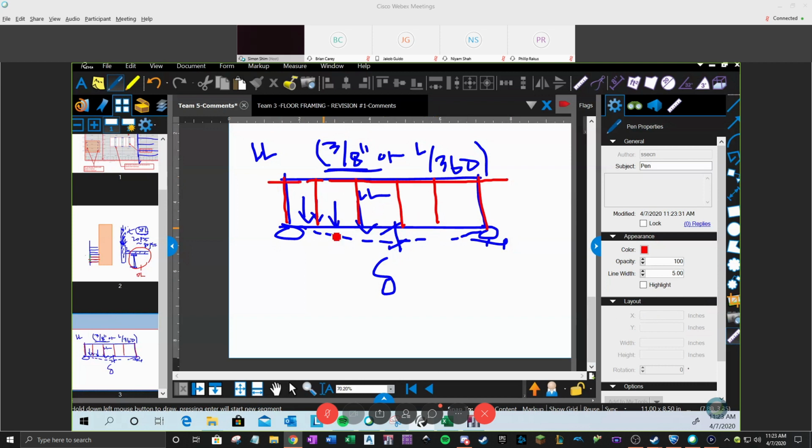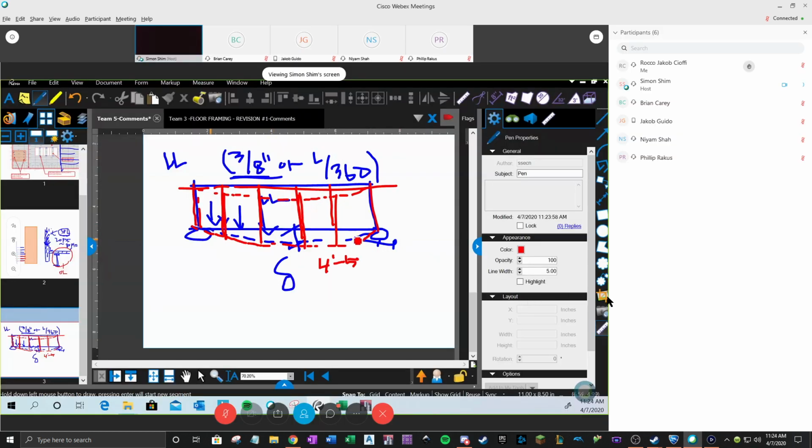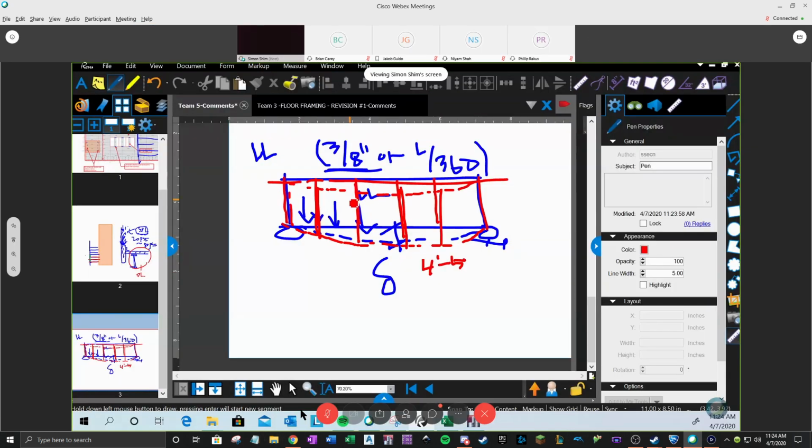It's not like our other structural elements when a beam deflects significantly. If this is a glass wall, we have vertical mullions, typically every 4 to 5 feet on center, which also follow and deflect. I'm exaggerating very significantly, right? So this is happening. When our spandrel beam supporting the enclosure material and glass wall deflects, all those non-structural elements deflect.